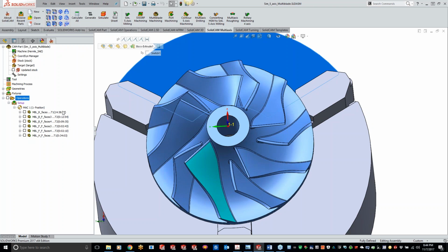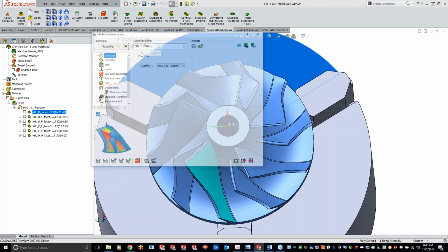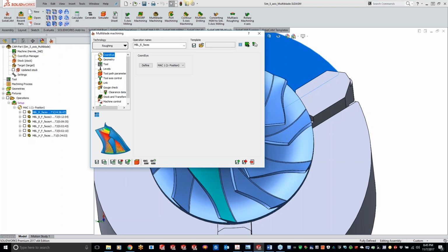So what I could do on this one too is, like I said, I haven't set any feeds and speeds with this particular part right here, but I'm wasting 14 hours on this. I got to get that improved. Boss is going to fire me. So, you can come back in here and maybe we don't need to do as many step downs, and I can get a little bit more of a stout end mill in there, or taper end mill, and take more hefty cuts in there. So that is nice. Thanks to Ronnie for reminding me about that one.